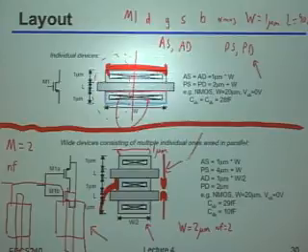Or did you mean something where there's some junction sharing going on? Okay, and in fact, even from a real SPICE model standpoint, if you literally had 2 transistors with some space in between them versus 2 transistors with a shared junction, those 2 are different. So just make sure when you're communicating with people that it's very clear you're both actually talking about the exact same thing. Okay?